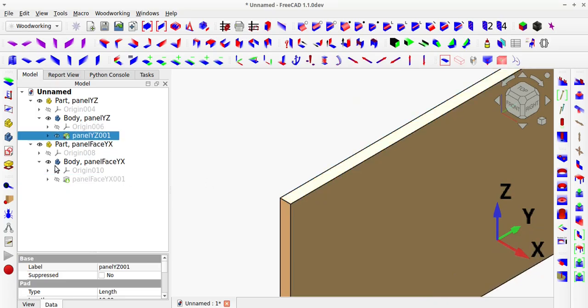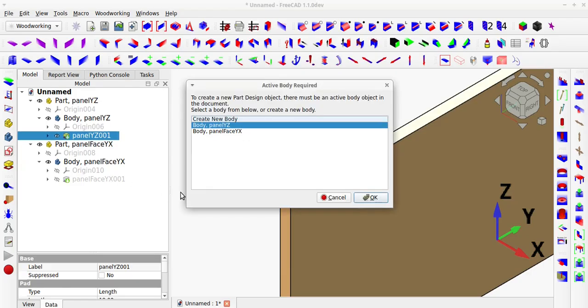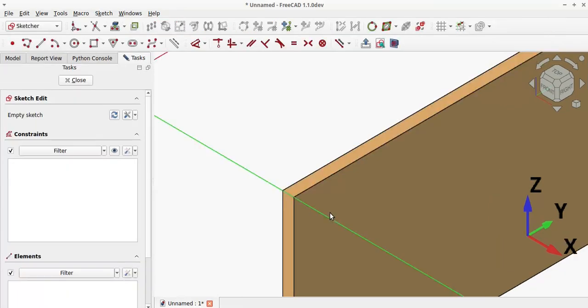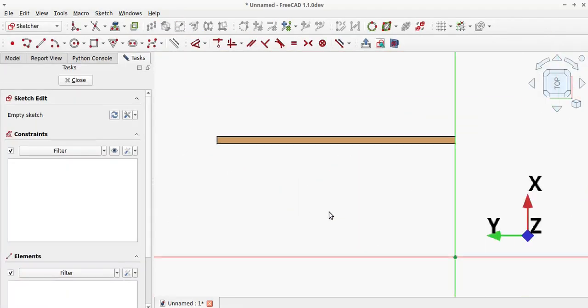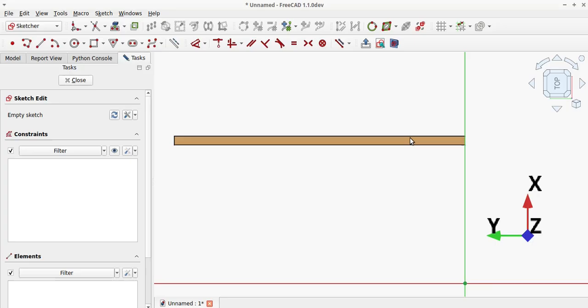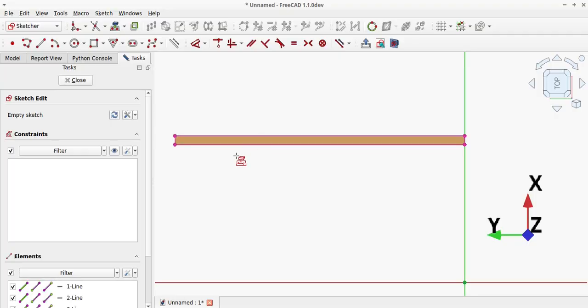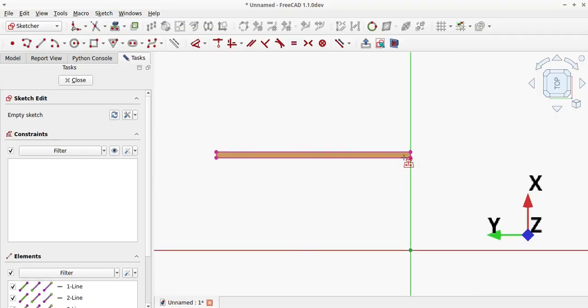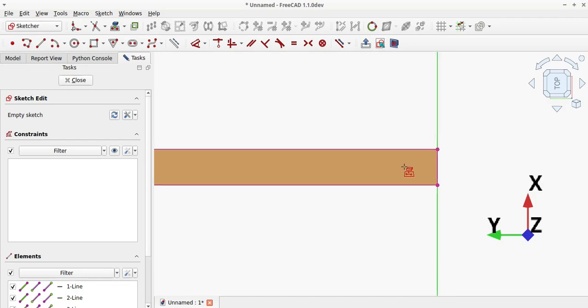With the magicJoints tool, you can use a sketch created directly on the face where the joints are to be created. This allows you to directly reference the object's edges through external geometry when creating the joint pattern.